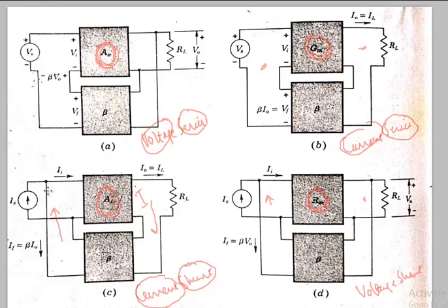Shunt will cause some current to be added or subtracted here at the mixing network. And finally, output, input. So output is expressed in terms of the parameter and input is expressed in terms of the configuration. So parameter is voltage or current, and the configuration is either series or shunt. But you need to understand what a series mixing means and what a shunt mixing means.